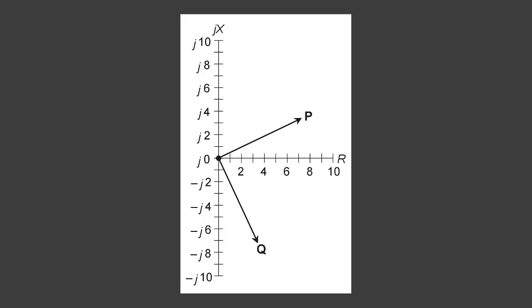So that's how that works, and we get impedance when we combine those 2 quantities mathematically, and we can graph them. They require 2 dimensions in order to be rendered properly. You can't render impedance in its full glory in only 1 dimension. You need 2 dimensions. You need the resistance dimension and you need the reactance dimension. Again, the correct choice is B.